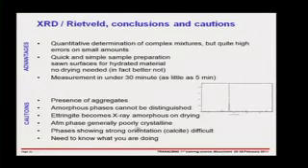Our AFm phases are also quite poorly crystalline. We can have phases that tend to be very small crystals that tend to orient in the plane of the sample, and therefore that causes problems for quantification. At the end of the day, as with most things, you need to know what you're doing. And hopefully, when we have the next course in a month's time, we'll be able to spend some time in the lab and really look at these different effects.